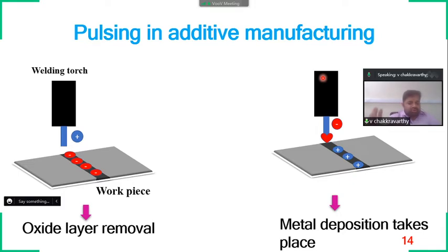Here, generally, we are using argon as the shielding gas. The argon gas will get polarized and charged, and that charged gas will be hitting the workpiece. Suddenly the arc constriction will take place, since the workpiece is positively charged, and the material deposition will take place. This is called straight polarity. In straight polarity, generally the material deposition takes place.